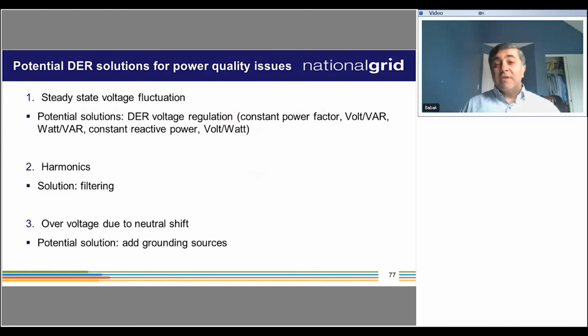So in terms of system performance, I should say volt-var provides benefits that will be seen by the system operators, but it's a little bit more complicated when it comes to implementing it compared to, say, fixed power factor or fixed reactive power mode. Complicated in the sense that volt-var functions need to be coordinated amongst DERs, and that requires some sort of communication system in place.